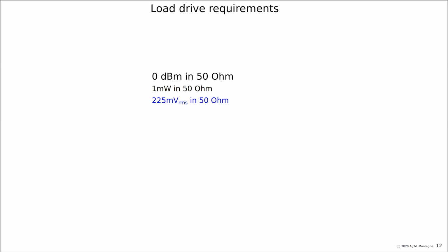But our amplifier is not going to drive root mean square values. It is driving peak values maybe. And now the question is, what is the peak value that it needs to drive in this 50 ohm? Assuming that it is a sine wave, it is about square root of 2 times the RMS value. Or does the signal look more like a Gaussian distribution, like noise? Then, if you want to have less than 3% clipping, your peak value can be 3 times sigma, the standard deviation. So it is much higher than for a sinusoid. So this is a question that might become interesting.